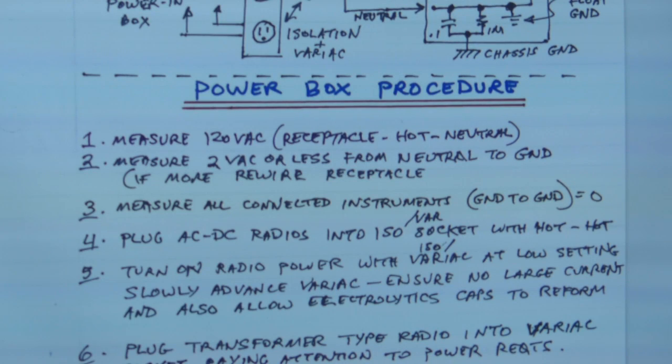All right, so you've got your setup, you've got your radio out there, and you plug them all in. Before you turn anything on, just measure the grounds between your box, the ground on the power receptacle, the ground in your radio, and the ground in the radio to the instruments that you're connecting up to it, like your oscilloscope, your generator, and whatever instrumentation you have. And you should be measuring almost 0 volts between all of those grounds.